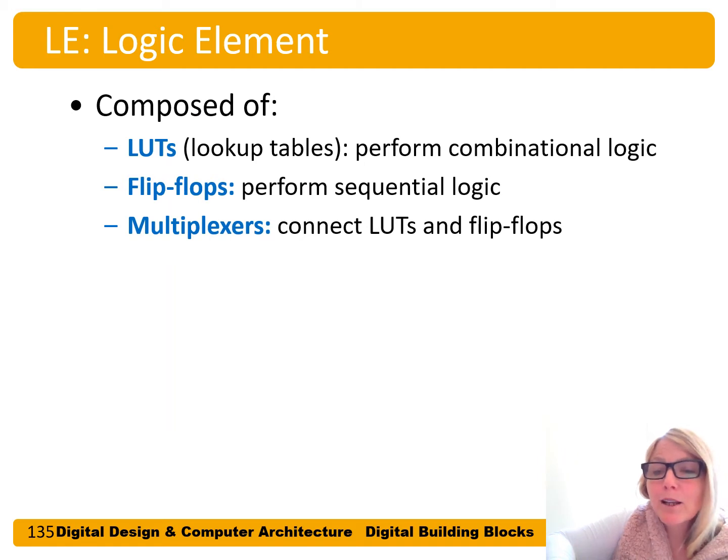So let's dive into what is inside of a logic element. LEs, these logic elements, are composed of lookup tables that perform combinational logic. This is what we talked about when we talked about memories, using them as lookup tables. That's exactly what the lookup tables are. They're very small memories. And flip-flops to perform sequential logic. And then we also have multiplexers that can connect these lookup tables and flip-flops together.